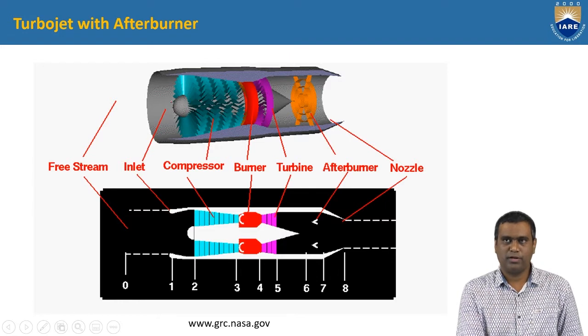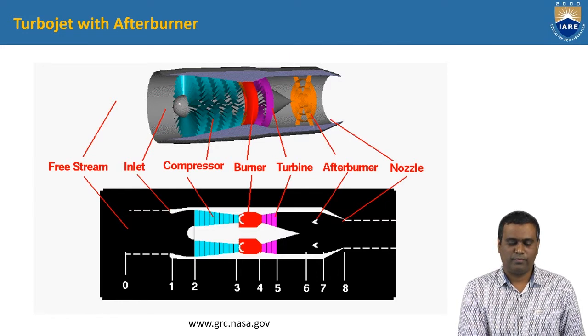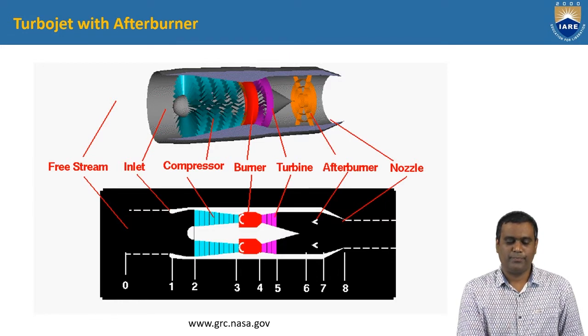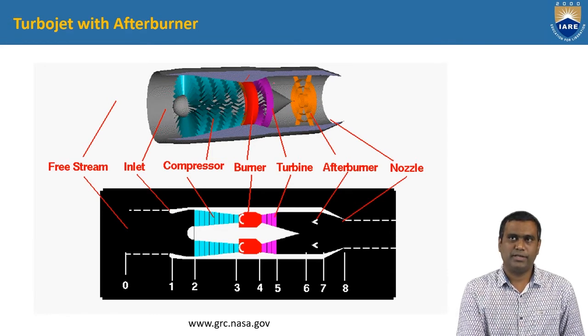See, as usual, the flow enters through the inlet and is compressed in the compressor, then sent to the combustors, where combustion takes place, and part of the combustion energy will be converted to mechanical energy by the turbine, and the remainder is exhaust. Actually, in this gas turbine engine combustion, an additional amount of air, additional oxygen, will be there generally.